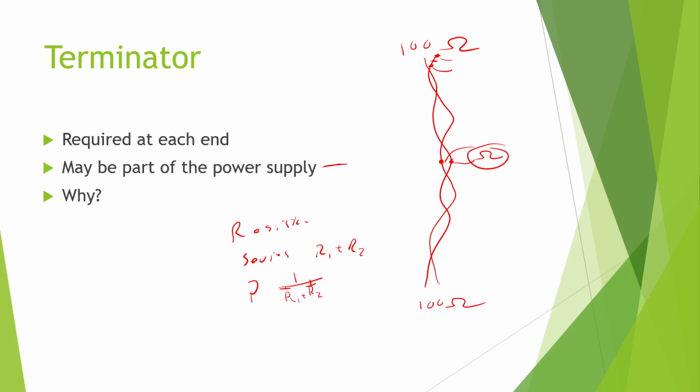All right. We also would do a quarter. This only needs to be a 1/4 watt resistor. We don't need a lot of power here. This is just dealing with signaling. It's just little pulses. Quarter watt's going to be plenty. That's your standard through-hole resistor size. I'm not saying you should just go to your resistor drawer at home, grab a quarter watt 100 ohm resistor and shove it on your network. But technically it would work.